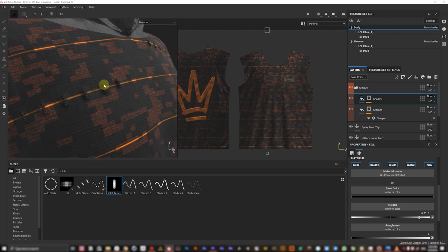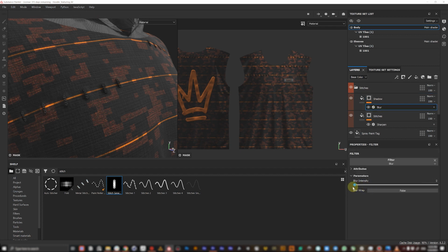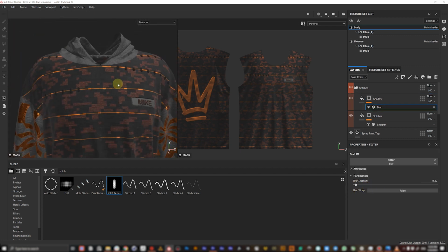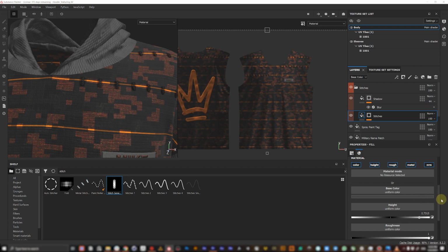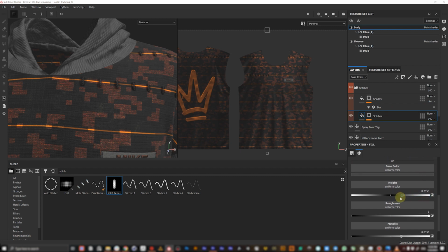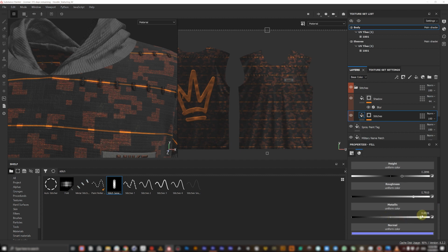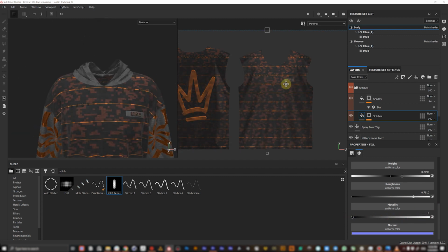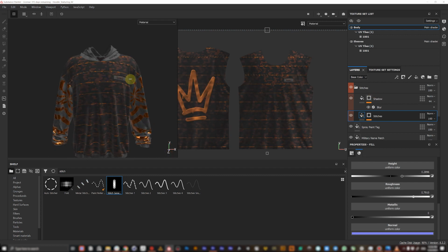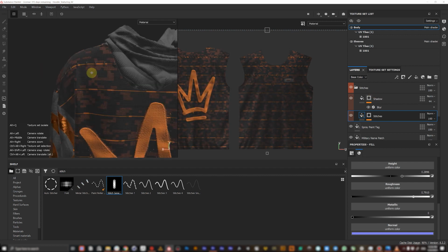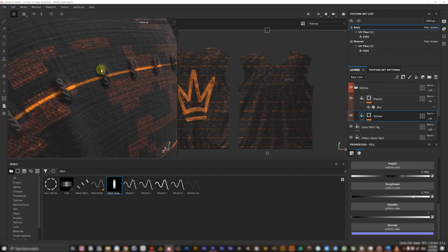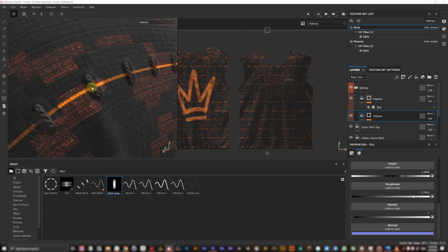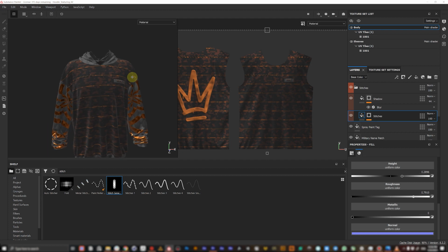So now we are pretty much getting something we are trying to achieve over here. I'm going to play just a little bit with the parameters on both shadow and actual stitches layer with some, I don't know, height, metallic, roughness to find the better look and feel. And don't forget to rotate your environment to see your actual model from different angles and from different light source. So I guess I'm pretty much happy with how the stitches is looking for now. It has those small opacity masks, is exactly what we needed.